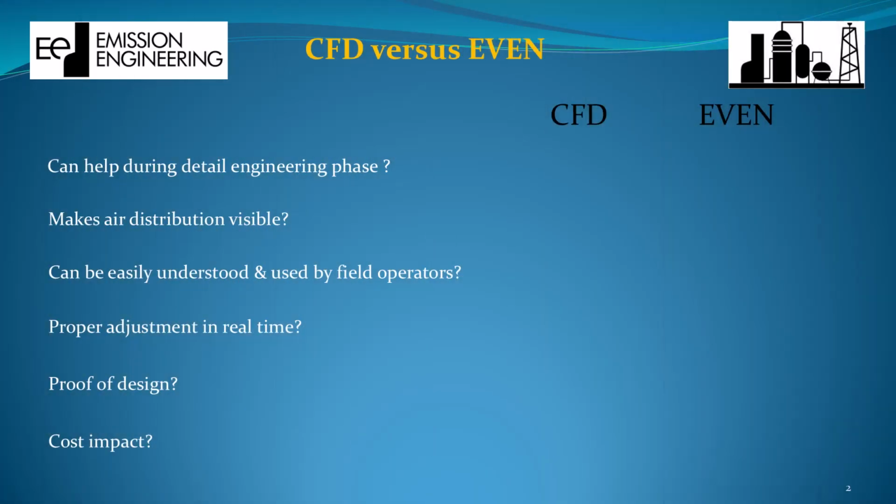Here are the pluses and minuses of both concepts. CFD can be, if properly used, a useful tool during the detail engineering phase to design the combustion air fan, air duct, and/or air dampers. As in any CFD study, it is crucial that the boundary conditions and system requirements are selected correctly. For example, it is nonsense to model flame shape, heat flux, or whatsoever assuming uniform air distribution to all burners, while this might not be proven. Even is not designed during a pre-operating phase of a furnace.